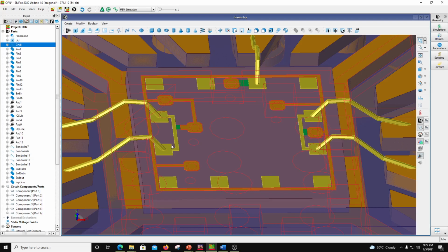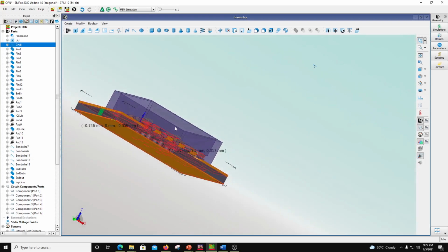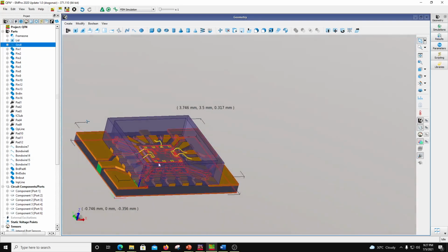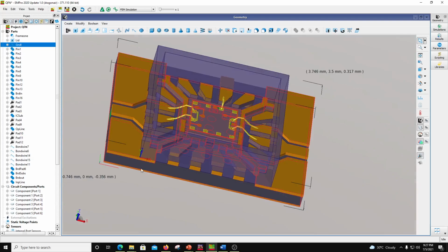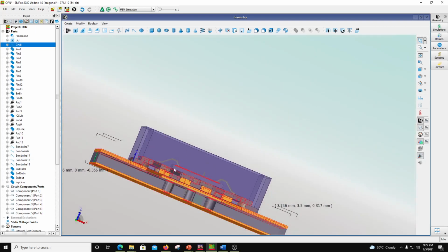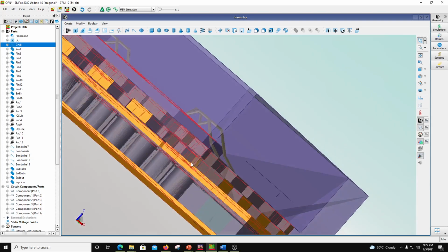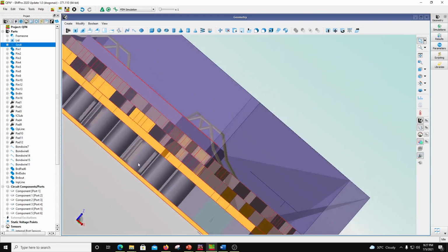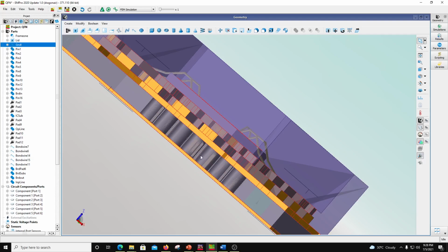Okay, so my real world starts from this box, which is 3mm by 3mm, and this sits on a Rogers laminate which you see here, right? And then this laminate is sitting on a bunch of vias, because that's how your ground comes in and that's how your heat goes out. Okay, so as a designer I start thinking from here.